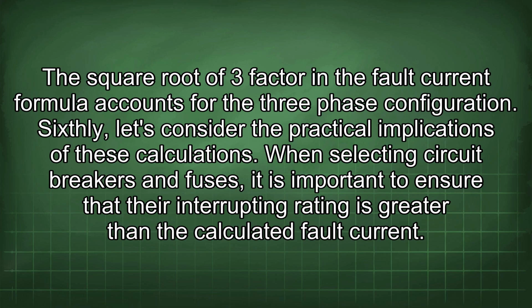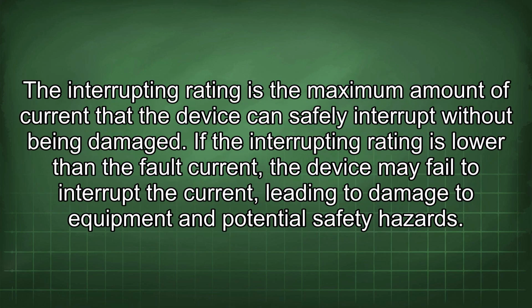Sixthly, let's consider the practical implications of these calculations. When selecting circuit breakers and fuses, it is important to ensure that their interrupting rating is greater than the calculated fault current. The interrupting rating is the maximum amount of current that the device can safely interrupt without being damaged.